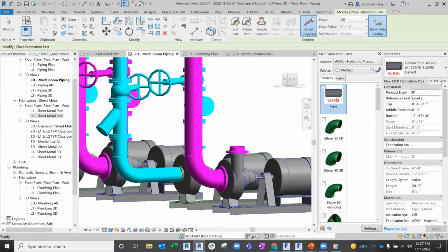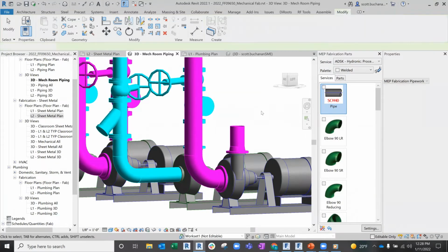So if I pick on that straight piece of pipe, all of our pipe, all of our duct comes in standard lengths to start. Based on the material, it would have that defined. If I was doing PVC, it might be 10 foot, or this one I've got is 20 foot, or maybe there's a 21 footer, but it's going to start with that. But that's where I can say, hey, I just want to do a little foot spool coming off of that, stick it on there, and I could keep going, right? So this is that kind of stick building that I mentioned.